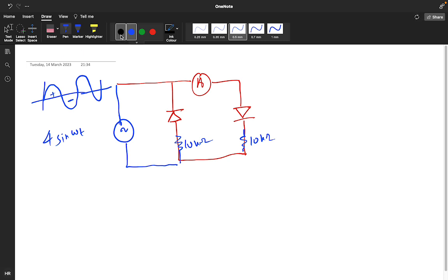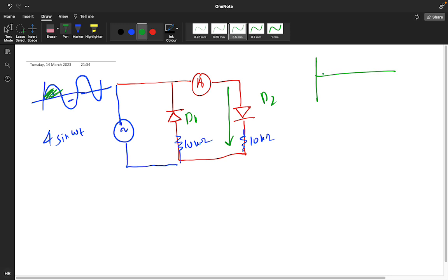So when the voltage is positive, which will conduct? This part will conduct, Diode 2. D2 will conduct, and this is your D1. If the diode is conducting, what signal, what graph are you getting? Like this, positive. What is the average value of this particular graph we derived yesterday? It was Vm by pi. So Vm is the given voltage, positive 4.